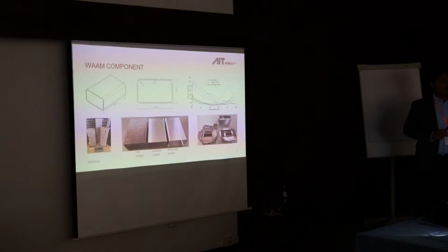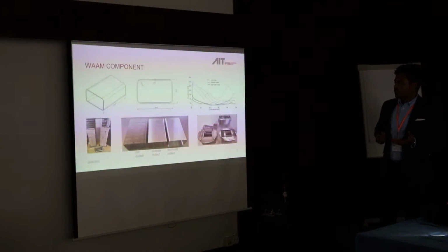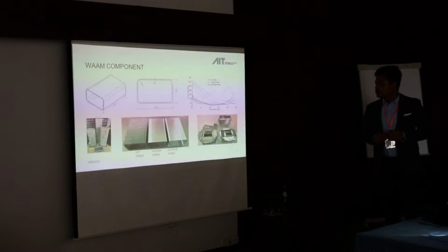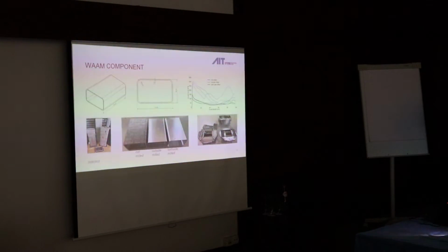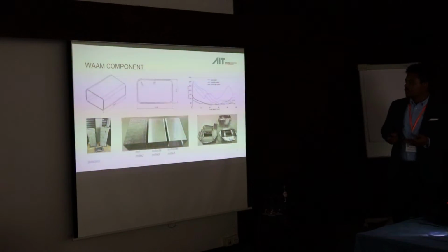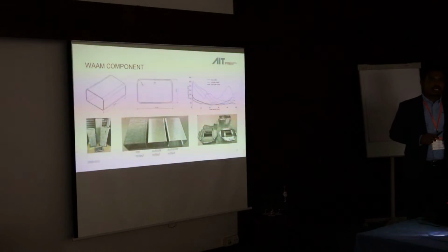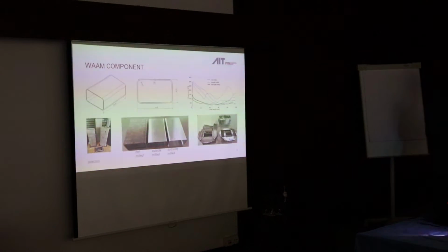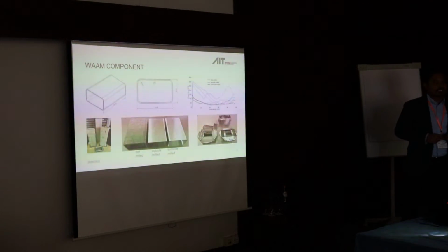The generic crash box that I mentioned, you can see from the very left side. This is how it looks after manufacturing. Then we cut at the top and the bottom. And we had three variations. The first one was not milled or machined, which is our most preferable variation because we do not want to spend time and money on machining. But we also wanted to try out the other two variations. In one case, we milled the outer surface to make the thickness a bit more consistent. In the third variation, we milled both surfaces, outer and inner as well. As a result, in the third case, we have a constant thickness, and there is no waviness on the surface.